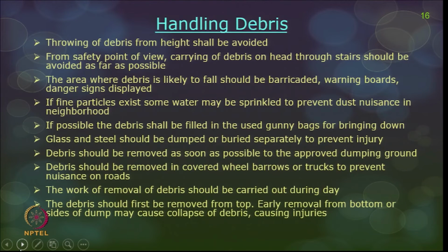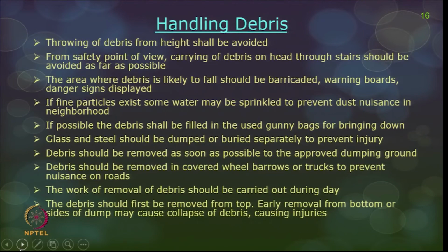The work of removal of debris should be carried out only during the day. Unless it is a very emergency, it can be carried out in the night, and again all other extra precautions have to be taken care of when the debris is handled at night. The debris should first be removed from the top, because if you start removing from the bottom, it can cause collapse of the debris, causing injuries.